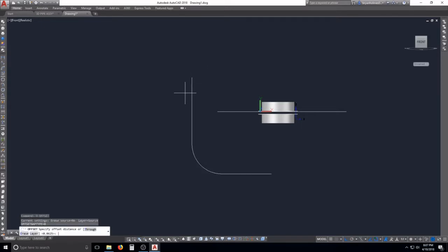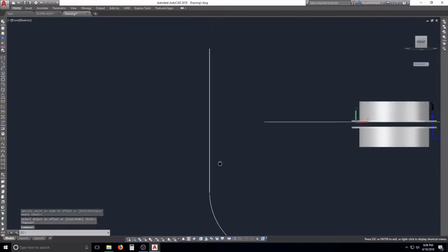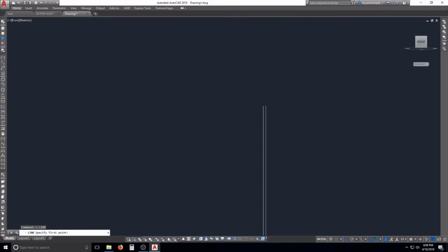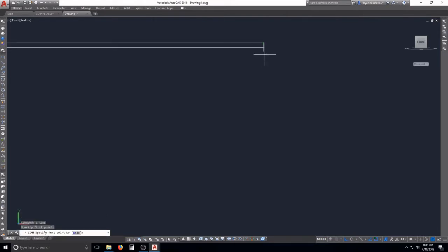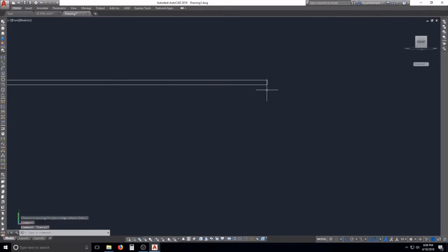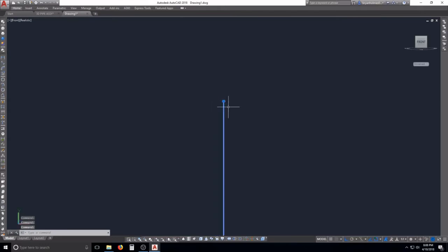So anyway, now that this is one piece, as you see there, we're going to offset it. It should still be a 16th, because it's going to stay the same. You couldn't see it, but it actually did it. Now what you're going to do is connect them. While we're up here, let's join these, and then we will do the same here. Line there, trim, because I'm lazy, didn't feel like doing a spot. Join again. So now if you click there, make sure you got little dots all over the place, and those are connected.